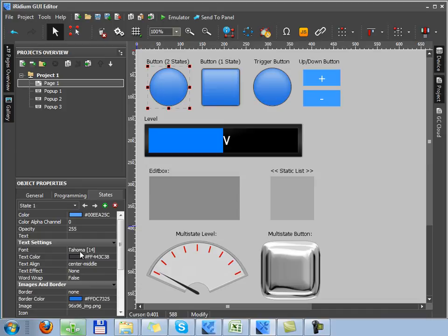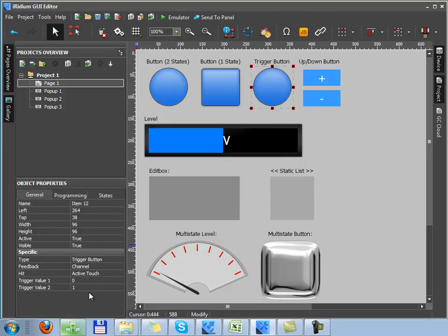Button with one state is used for sending values to the graphic item. To indicate value on button with one state, you can use templates of processing and outputting data on graphic. Trigger buttons are used for switching variables from active to non-active state. Trigger button can be also used for switching any two states with one button, which are indicated in the properties of trigger.